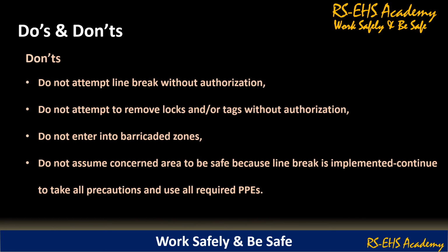Line break process don'ts. Do not attempt a line break without authorization. Do not attempt to remove locks and or tags without authorization. Do not enter into barricaded zones. Do not assume the concerned area to be safe because a line break is implemented. Continue to take all precautions and use all required PPEs.